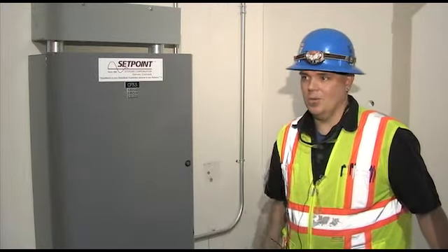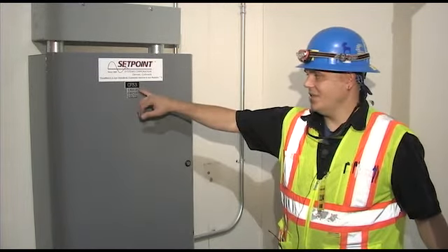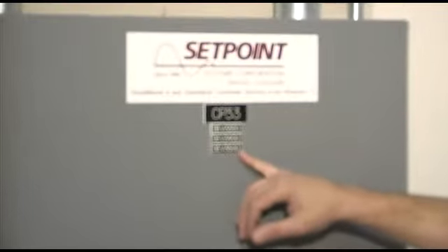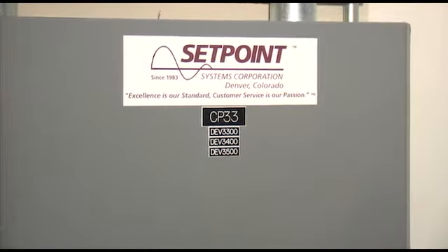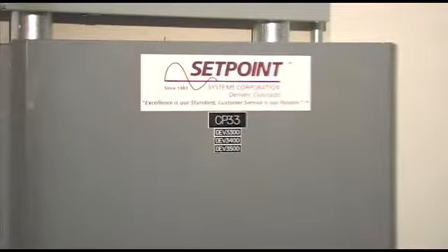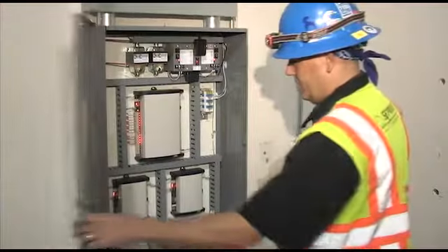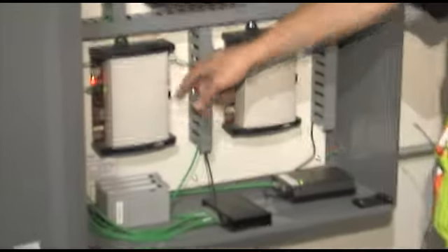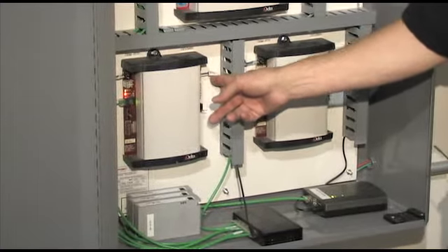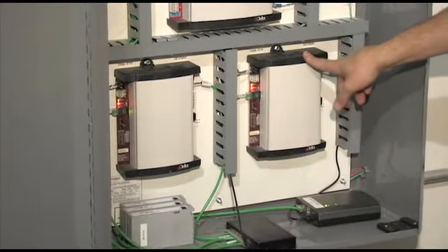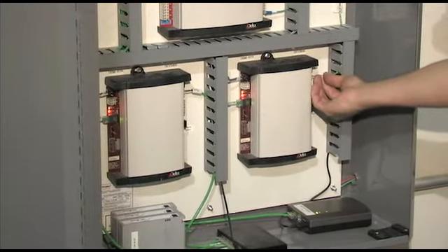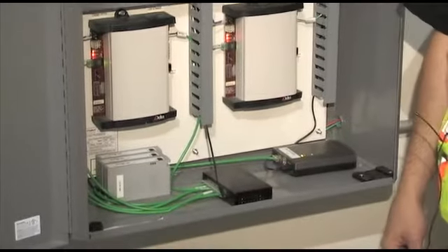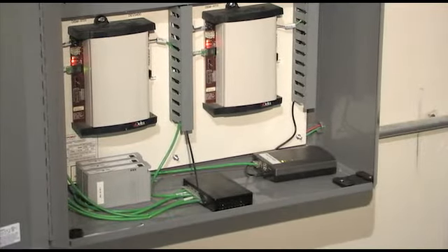Upstairs in the air handler room for the NEC, we have CP33 with device 3300, device 3400, and device 3500. 3400 and 3500 are our two Modbus interface panels for the RPPs and PDUs. Device 3400 is on the left, and this one is our interface through this comm line to the RPPs. Device 3500 is on the right, and it is our Modbus interface to the PDUs. Tied into our network switch back into the existing Delta network on campus.